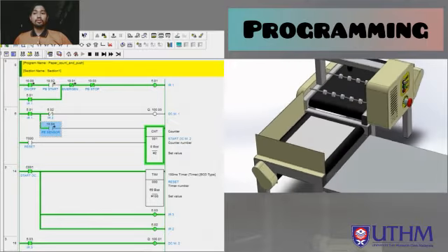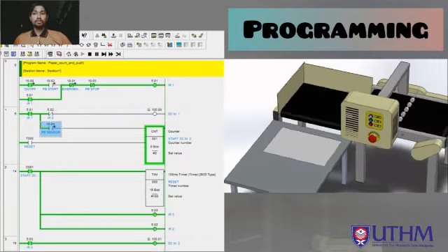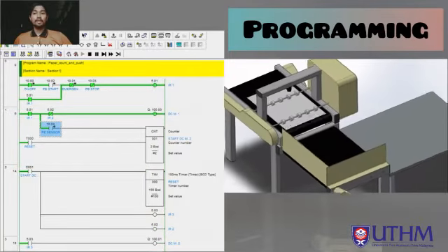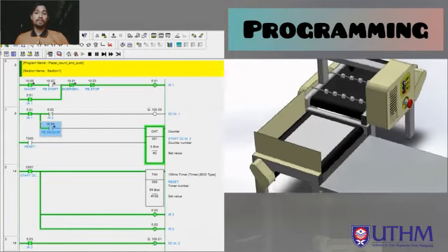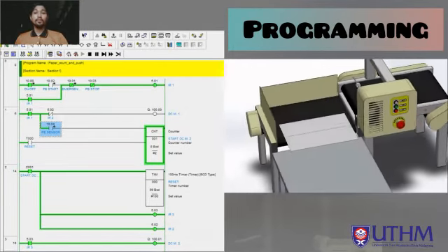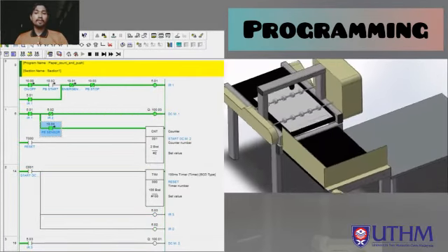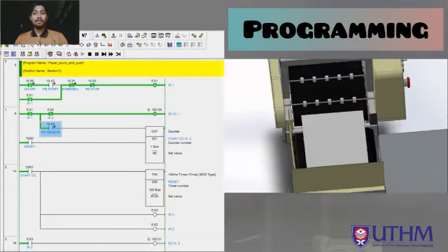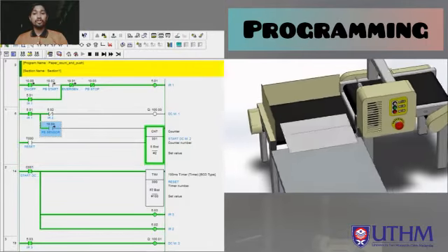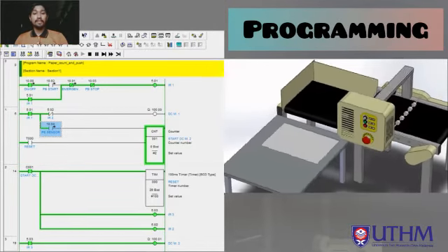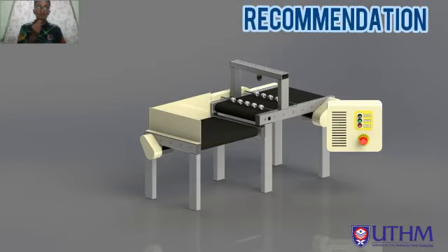When the countdown is over, an internal timer will be triggered, pausing the conveyor 1 DC motor and enabling the conveyor 2 DC motor. This timer will provide enough time for conveyor 2 to transport the paper to the next station, while preventing new paper from piling up during the process. After the timer runs out, the internal counter will be reset to 0 and the same process will repeat again in a loop.